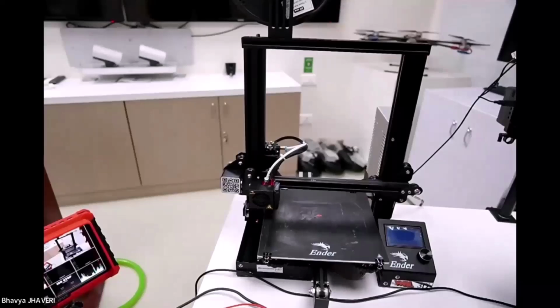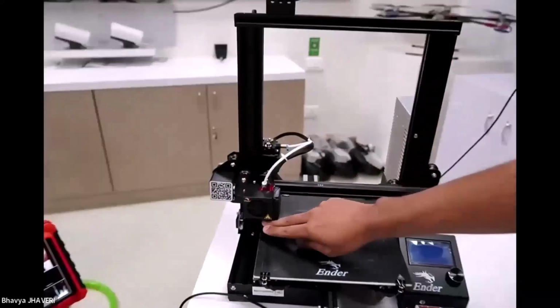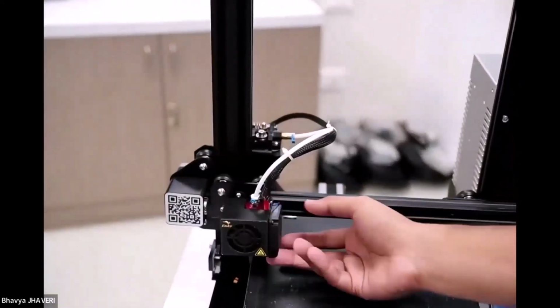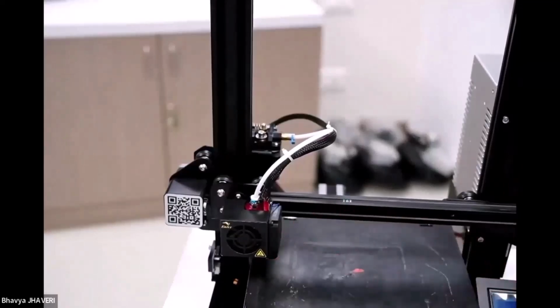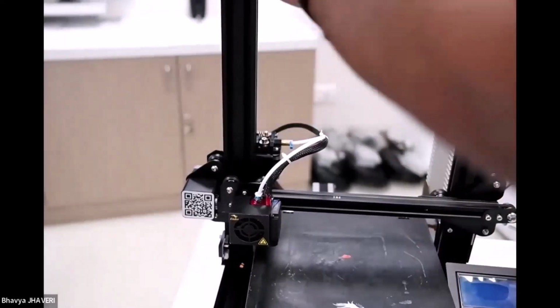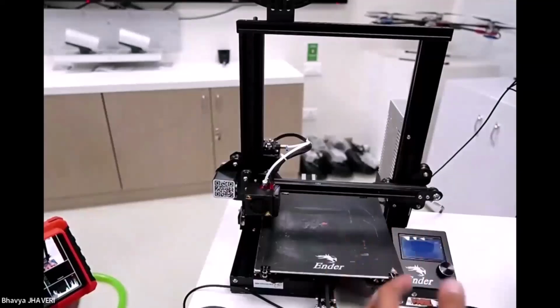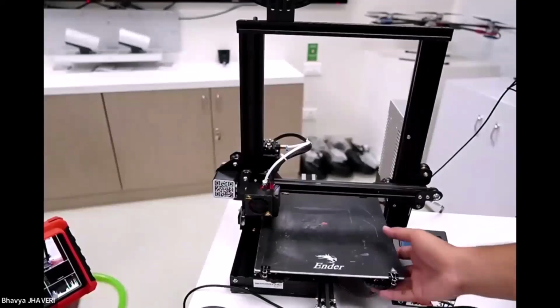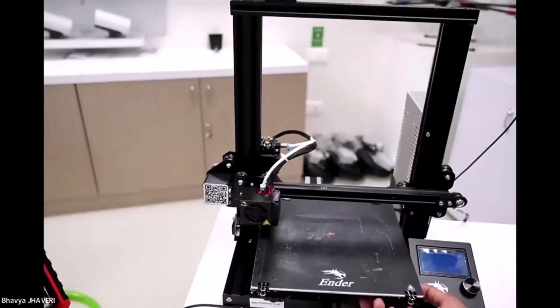In order for this to be heated, we will have to connect it with the hot end, and here is nothing but the nozzle. At the end, this nozzle here is going to extrude the material, and this is the first thing for setting up a 3D printer. The first thing you need is a filament, and a printer with a nozzle which is hot and preheating. The next thing would be bed leveling. For bed leveling, we have levels here. What happens in bed leveling is that we can set the bed level.